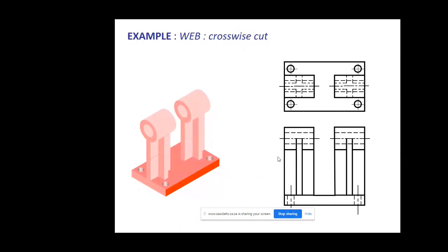So, as you can see, this is one resource that can make things much, much easier. Now, for you to draw a full sectional top view, you need to cut the whole object from the front, using that particular cutting object. So after doing that, what happens now? This is in third angle orthographic projection. For you to see the top view, you must look at these things from the top. So in other words, you need to imagine this top part that is being cut to be removed, and the remainder of what will be there is your top view.